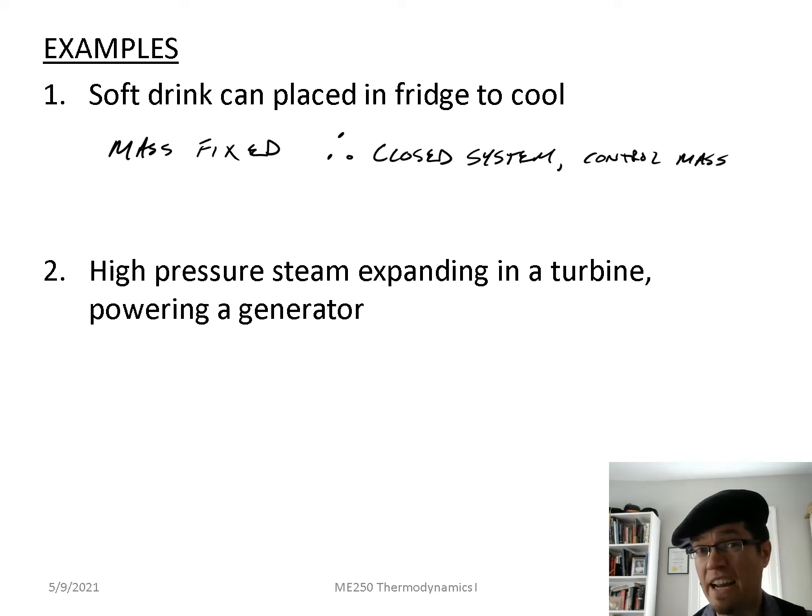It's not adiabatic, especially if you're trying to model the cooling of it in a fridge or the heating of it on a counter. It's not fully rigid, because obviously you can squeeze a can and it can change a bit, but it's pretty rigid. So you would probably model it as a rigid, non-adiabatic closed system, unless you were caring about the stretching of the can as it heats or cools, and the stresses that generates on the wall of the can.